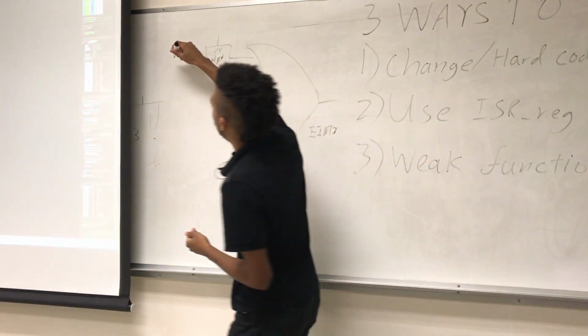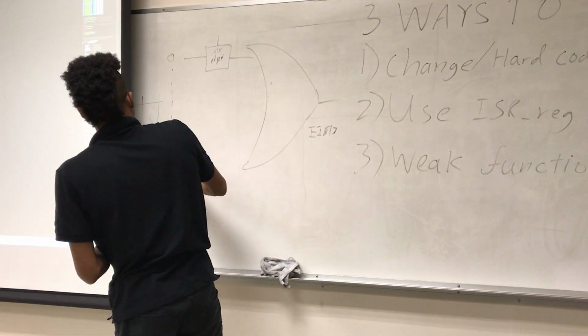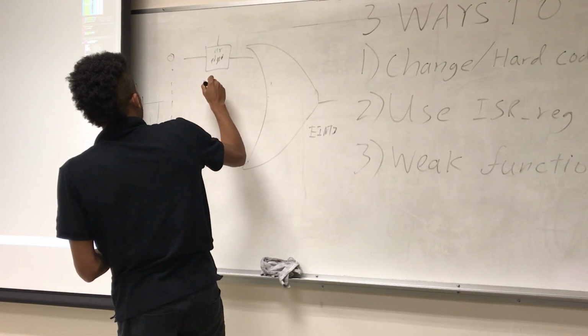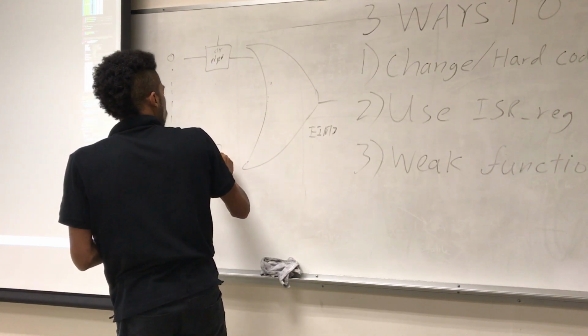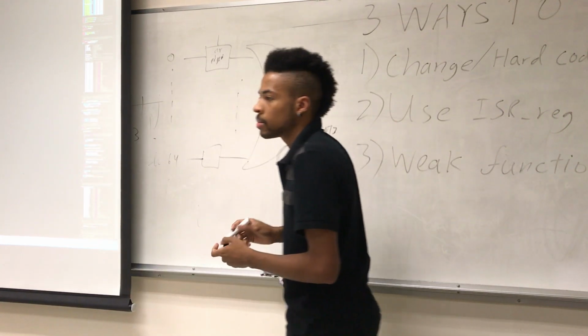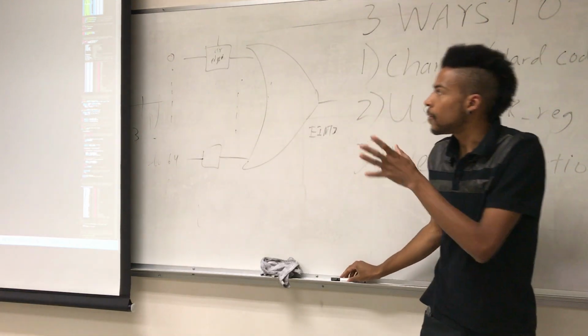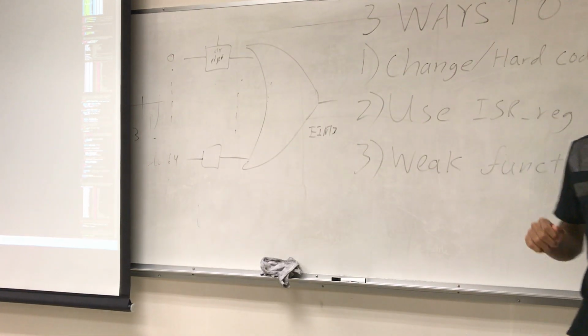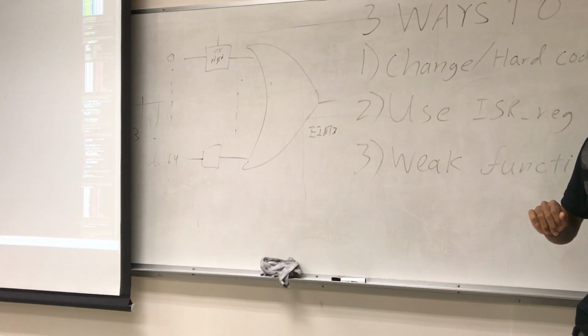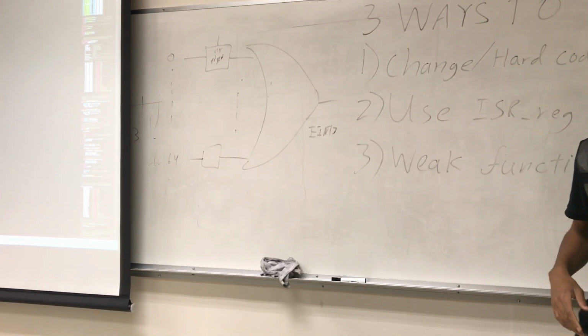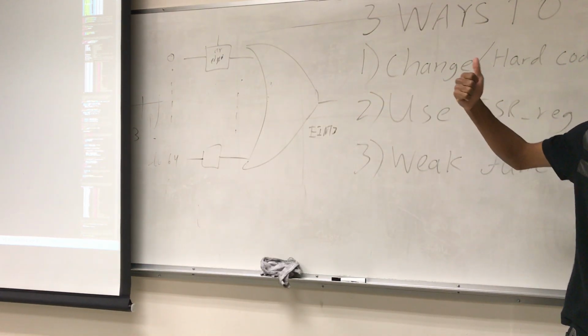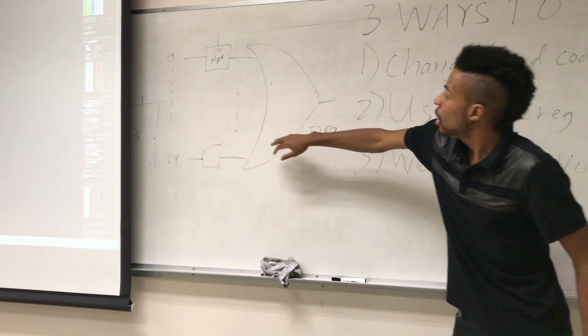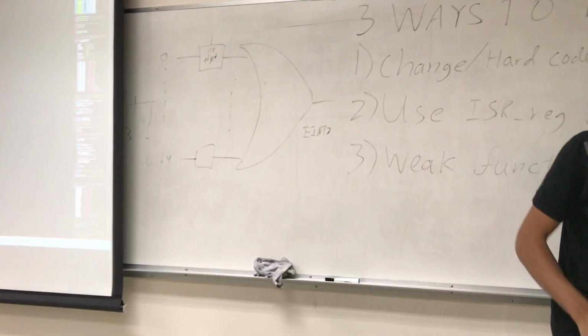And it just takes each GPIO from 0 to 64 if you count them synchronously. You just take all those in. That's effectively what should be happening. If you have either a rising or falling edge, depending on how you set up your interrupts, if any one of these flags is set, this guy will catch it, and then this service routine will happen.